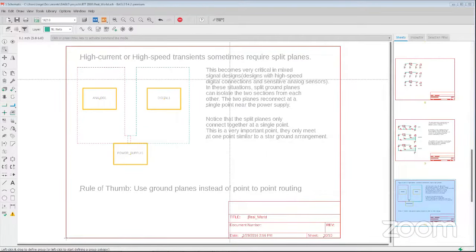Any plans to release a new tool for length matching? The meander command covers length matching pretty well. The only thing we would want to do is something that could do the impedance calculation, because then you could do a more accurate impedance match.